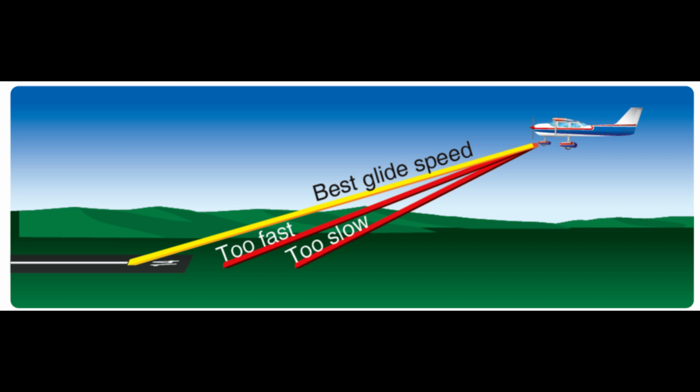These three factors make it necessary to use more back pressure on the elevator than is required for a straight glide or a level turn, and they have an effect on control coordination. The rudder compensates for yawing tendencies when rolling in or out of a gliding turn. However, the required rudder pedal pressures are reduced as a result of the reduced forces acting on the control surfaces. A learner may apply excessive rudder pedal pressures based on experience with powered flight.